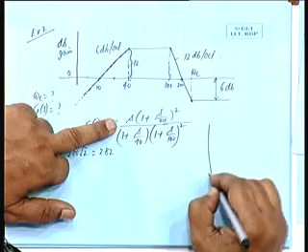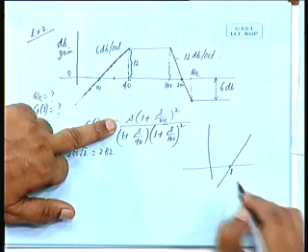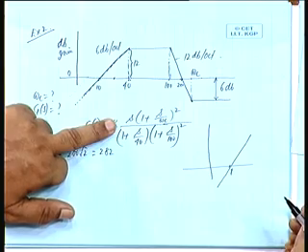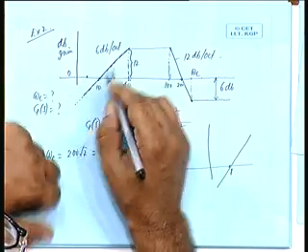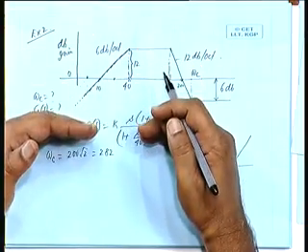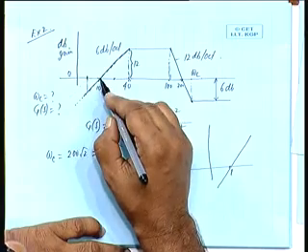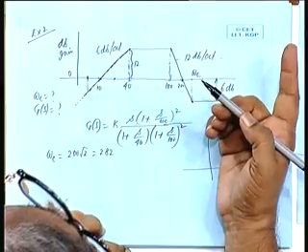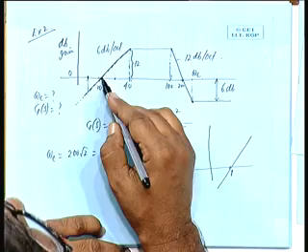S is a plot which is passing through omega equal to 1, is it not? Now, instead of passing through omega equal to 1, it is passing through 10, that means this is brought down by how much? It is 1 decade, 1 to 10 is 1 decade, 1 decade corresponds to 6 dB per octave, which is equivalent to 20 dB per decade. So, in 1 decade it is 20 dB.